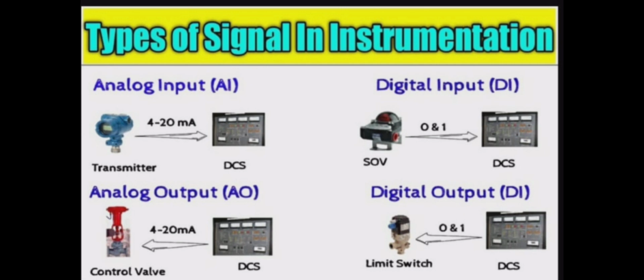Now, what is digital output? Digital outputs are binary outputs, 0 or 1. The name digital itself indicates 0 or 1 from the PLC. It provides the control output from the PLC to the field. As it is named, it is digital output. So it is used to switch on and off pieces of field equipment.